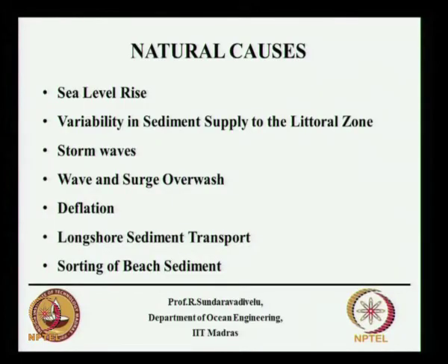Storm waves: when the wave height is more, it carries more sediments and then creates erosion. Then we have wave and surge overwash. Surge means when the cyclone is crossing, there is a certain amount of water which is going into the land. Then we have other cases like deflation, longshore sediment transport, sorting of beach sediment, etc.